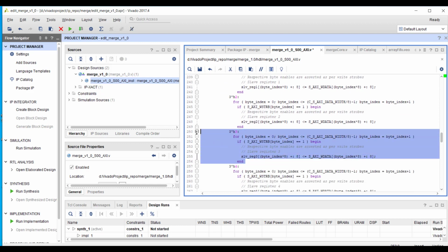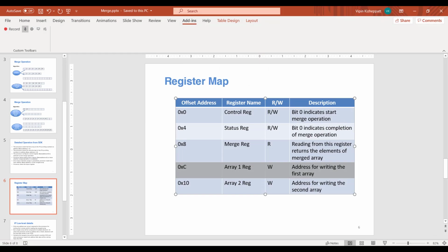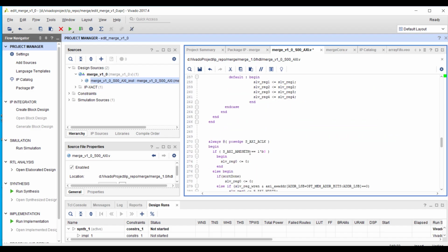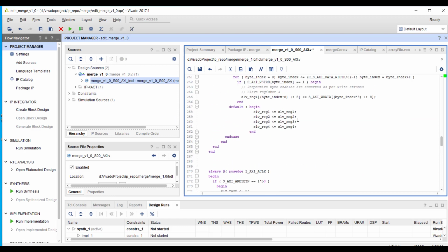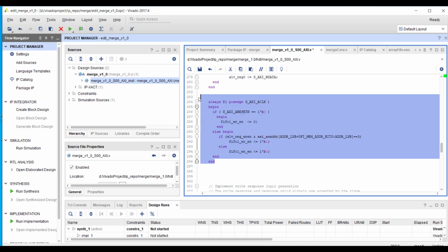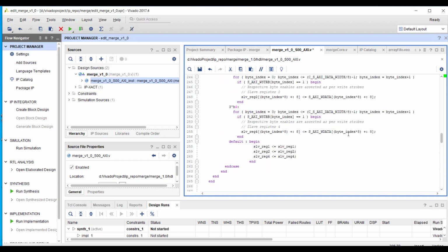So slave reg 3 can go. And same way this will be 16 and here it is slave reg 4. So same logic you can replicate for FIFO 2 write enable, when the processor writes to address 4. So this can also go from here.